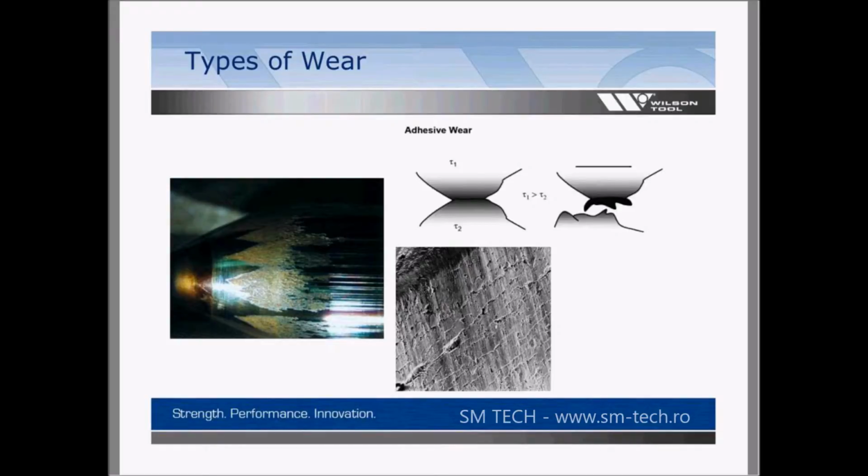You can see the machine lines in that surface finish of that punch. Being able to polish them out would be a critical aspect of changing your tool steel. So if you were to go to a harder steel, like a 10V or something like that, making sure you're able to still clean up and machine that properly. So your tooling itself, you're using to do all your manufacturing, your radius, your cutting tools, and your grinding wheels. The surface finish to begin with is critical at that point. So a 10V is a lot harder to machine than say an A2 would be. So keep that in mind when you do go change steels.